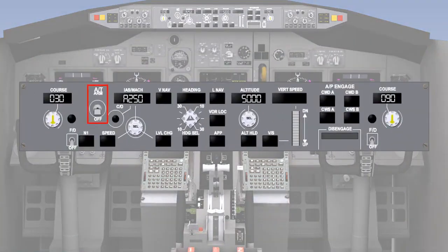In this lesson, you will learn about the pitch or secondary axis flight path modes used by the Autopilot. In most modern airliners, there will be an auto throttle system, which will operate in conjunction with the pitch channel of the Autopilot to control climb, cruise and descent functions.